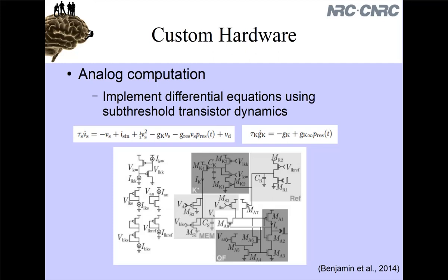There's been, however, a reason that people tend not to do analog computation. One big issue that traditionally comes up is, hey, even if you write out that circuit and then manufacture that chip with, say, thousands of that circuit on it, the manufacturing process isn't perfect. I mean, you start counting the number of atoms involved in these transistors, and they're not perfectly aligned. There is variation in the manufacturing process. There is what they call transistor mismatch. So when you manufacture a chip, you say, okay, I want this transistor to have this particular property, resistance, capacitance, things like that.